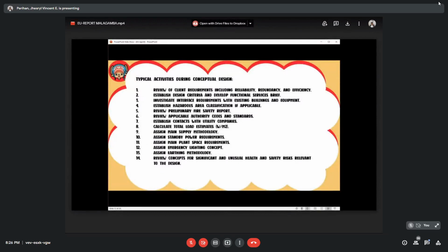Sixth, review applicable authority codes and standards, the PEC or NEC, the National Electrical Code or Philippine Electrical Code. Seventh, establish contacts with utility companies. Eighth, calculate total load estimates. Ninth, assign main supply methodology.